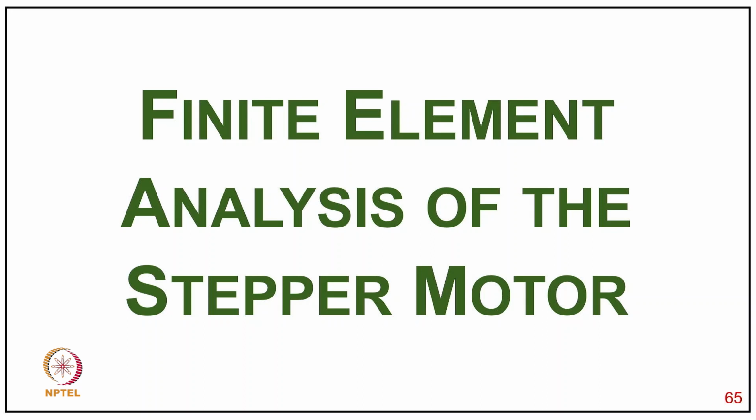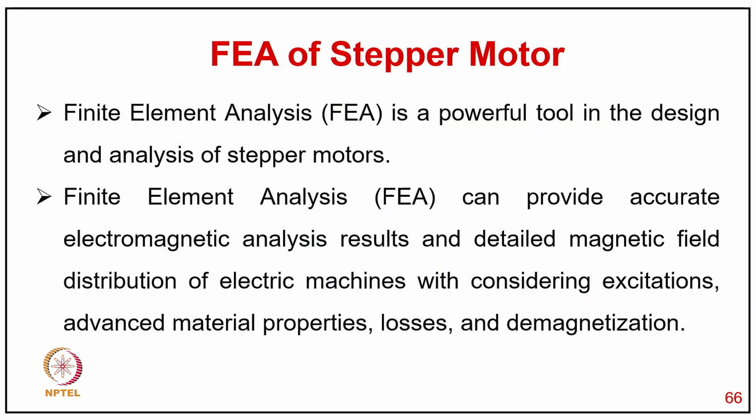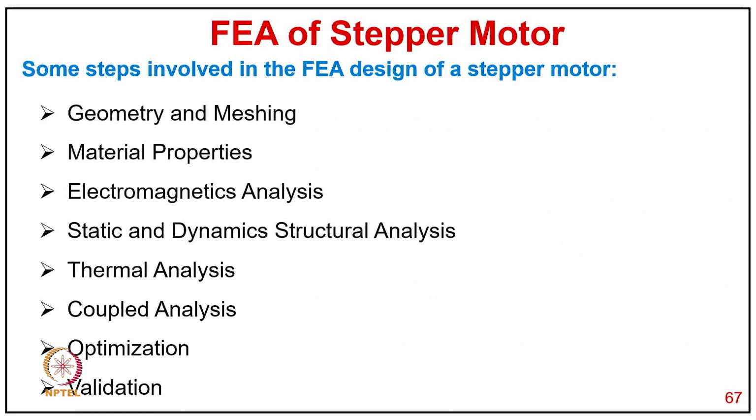Now coming to finite element analysis of the stepper motor. Finite element analysis is a powerful tool in the design and analysis of stepper motors. It can provide accurate electromagnetic analysis results and detailed magnetic field distribution of electric machines, considering excitation, advanced material properties, losses, and demagnetization. Some of the steps involved in finite element design of a stepper motor: geometry and meshing, material properties, electromagnetic analysis, static and dynamic structural analysis, thermal analysis, coupled analysis, optimization, validation.